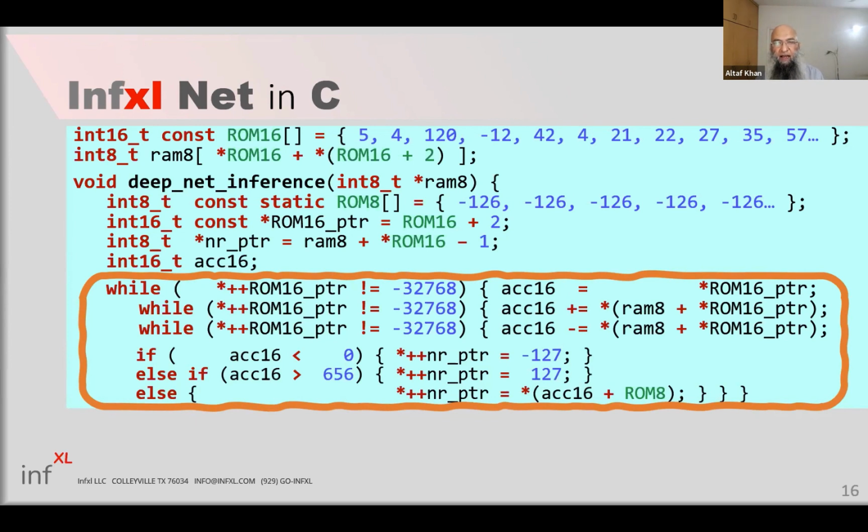And this is highly tuned in the sense that it's really optimized for FPGA implementation, because floating point operations take a lot of space. A floating point multiplier takes a lot of space. So we have gotten rid of both of those things. All the data paths are either 8-bit or 16-bit. So a very small footprint for this FPGA.